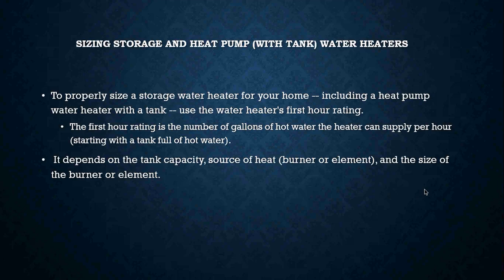It depends on the tank capacity, the heat source, and the size of the burners or elements. That is what's going to determine my first hour rating, the number of gallons of hot water that this water heater is actually going to be able to deliver.